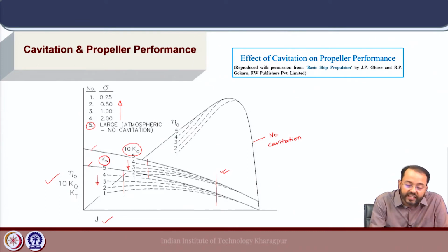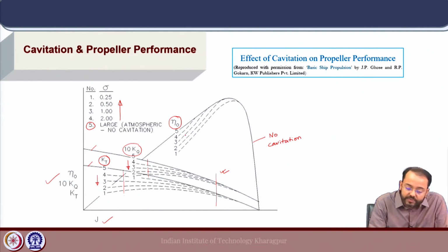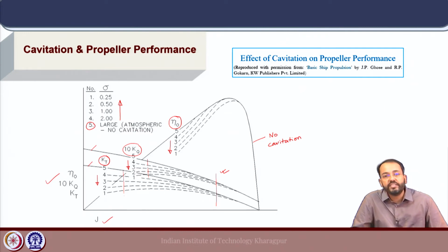Similarly, we can calculate the effect of cavitation on the open water efficiency by the resultant of the new thrust and torque that we get after cavitation occurrence, and it is observed that similarly the efficiency is also reduced as the cavitation occurrence increases on the propeller blade. That is one of the main reasons why cavitation phenomena should be avoided if possible in the design stage of the propeller as much as possible, so that the propeller blade performance is not affected in critical operation conditions.